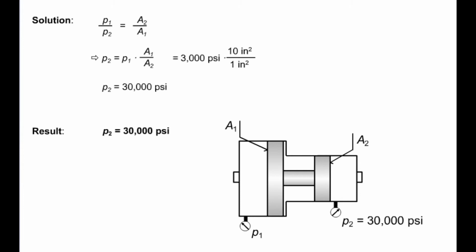This concept is used in industry, in particular in the process known as hydroforming, in which components are deformed under the application of very high pressures. The effect can also work in a negative sense, for example with so-called differential cylinders with a single piston rod. If the volume of fluid displaced from the annular area on the side of the piston rod faces a resistance such as a flow control valve, proportional to the areas, it is possible to cause high excess pressure on the rod side of the piston.